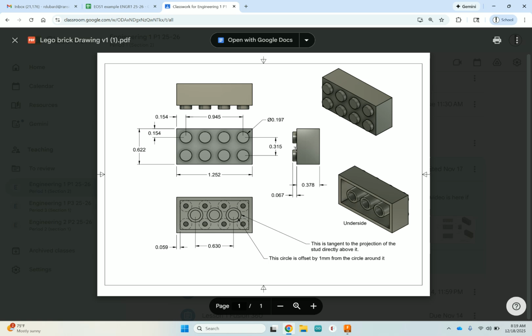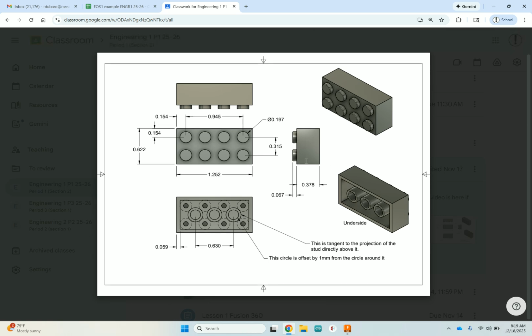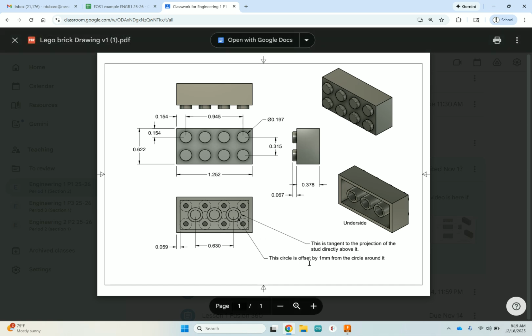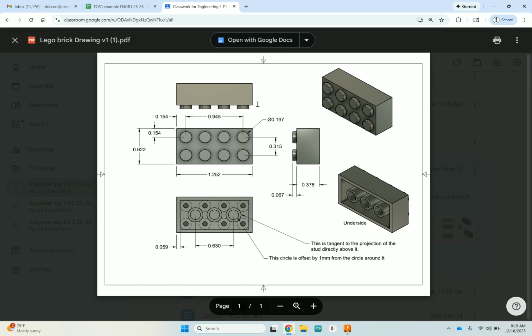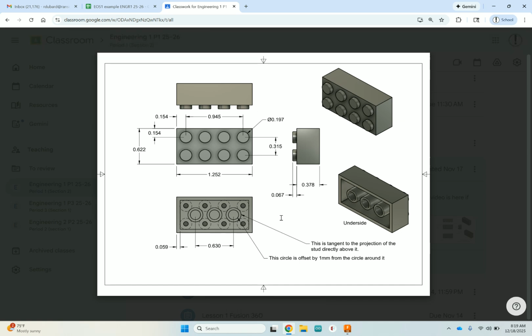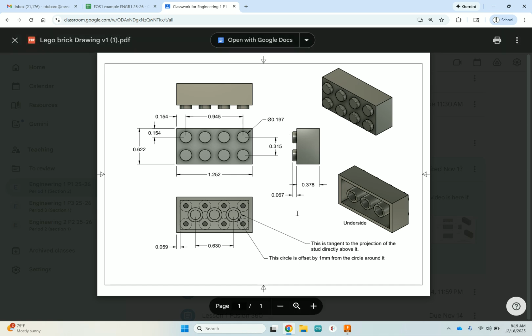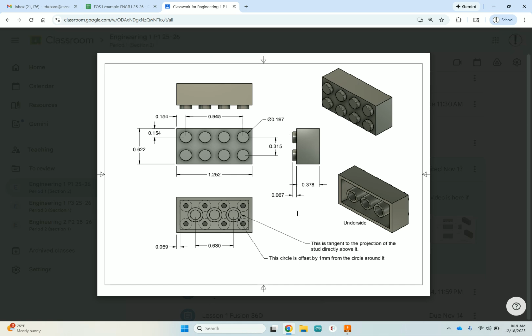I don't know if you can tell that too well by looking at this, but there's a slight curvature right around the top edges of this. And that curvature, does it tell you in here the size of it? It doesn't. So this drawing is deficient in that it doesn't tell you the size of those fillets, but it's 0.2 millimeters, I believe it is. That'll be fine if you do 0.2 millimeters, as long as it's something fairly small.